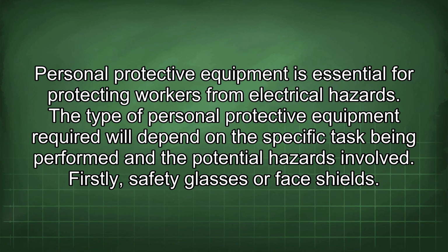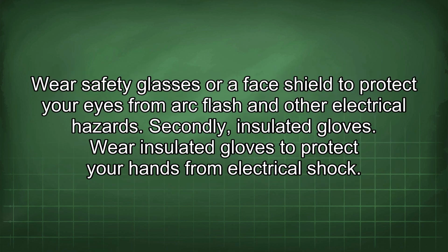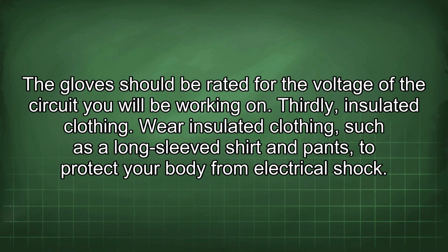Firstly, safety glasses or face shields. Wear safety glasses or a face shield to protect your eyes from arc flash and other electrical hazards. Secondly, insulated gloves. Wear insulated gloves to protect your hands from electrical shock. The gloves should be rated for the voltage of the circuit you will be working on.